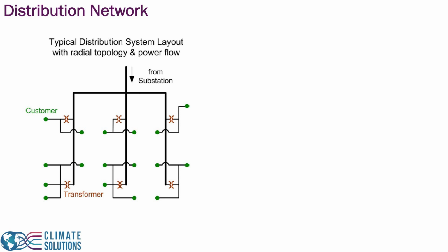In distribution networks, we also observe that the currents flowing from the substation to consumers are going to be higher because the voltages are lower for the same amount of power. This means that we observe significant drops in voltage magnitude as the current flows through the network.